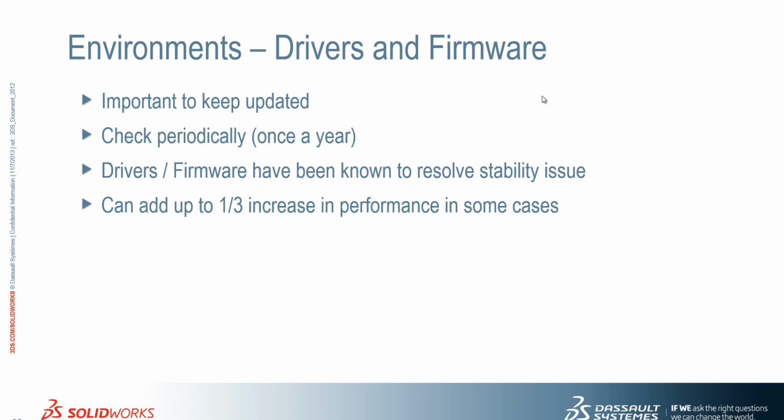Windows Update has seen this and installed it without your knowledge, and then, for instance, we get phone calls saying we've got weird things happening on screen, and the first thing we ask is, have you checked your graphics driver? Getting ahead of yourself, using a graphics driver which is too new, can actually produce problems. So I say always try and keep it in line with whatever SolidWorks say.